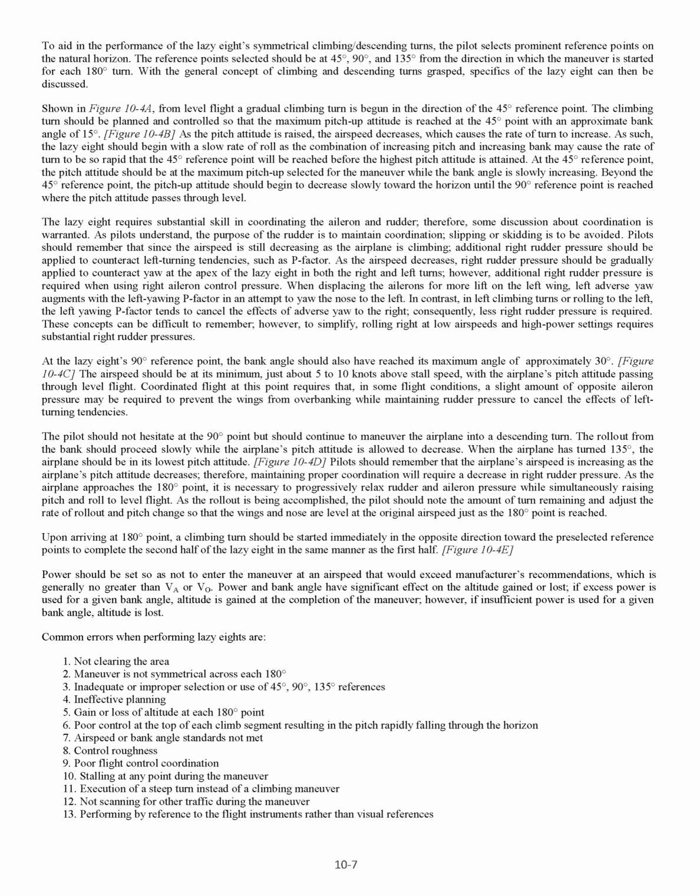At the 45 degrees reference point, the pitch attitude should be at the maximum pitch up selected for the maneuver while the bank angle is slowly increasing. Beyond the 45 degrees reference point, the pitch up attitude should begin to decrease slowly toward the horizon until the 90 degrees reference point is reached, where the pitch attitude passes through level.